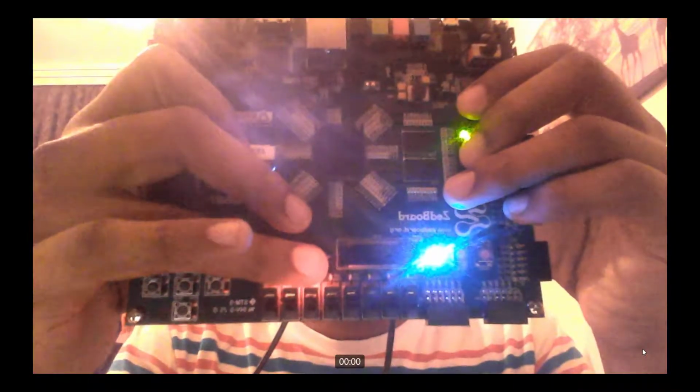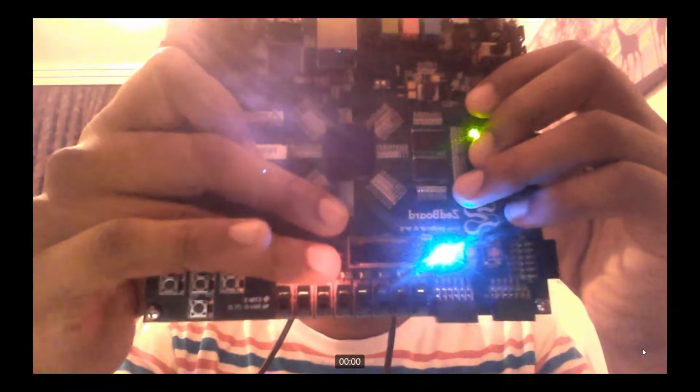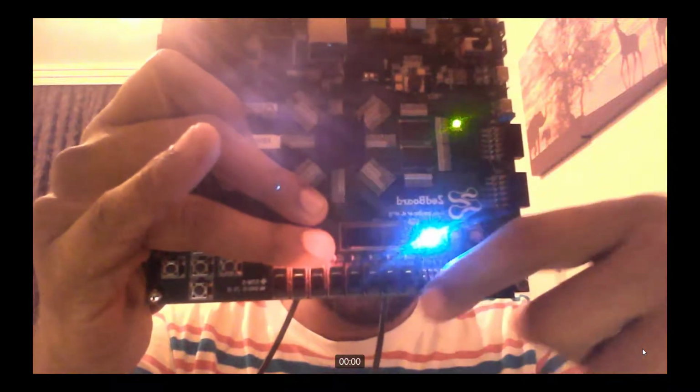These two LEDs correspond to the serial clock and the serial data that we assigned. Remember, when the clock is not active, it is always 1, and when the data is not active, it can be 1 or 0 depending on the previous state. These are the slide switches used for specifying the input data, and currently all of them are off.